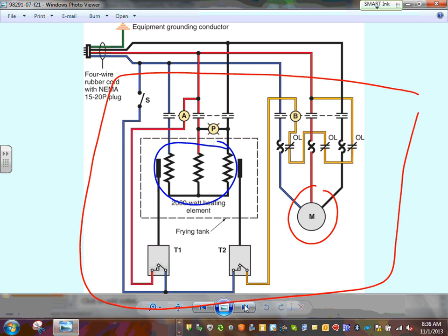So this happened to be a control wire for the donut machine. You need a heating element for your donut machine, and a mixer and heat and what not. All this, we don't get involved in. We don't design the inside of it. What we get involved in is right in here: we have to provide a disconnect to the machine, an overcurrent protection device, and a feeder. Inside the machine is designed by others. Doesn't mean we don't know how it works, but it's designed by others.